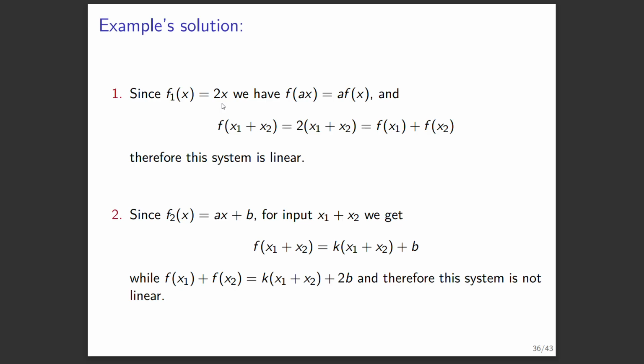If I describe my system as having x as the input and f as the output, and I want to check linearity, I can check to see if it's scalable and if superposition holds. So if I make my input x 8 times bigger and check if f of 8x is equal to 8 times f of x, that means it's scalable.